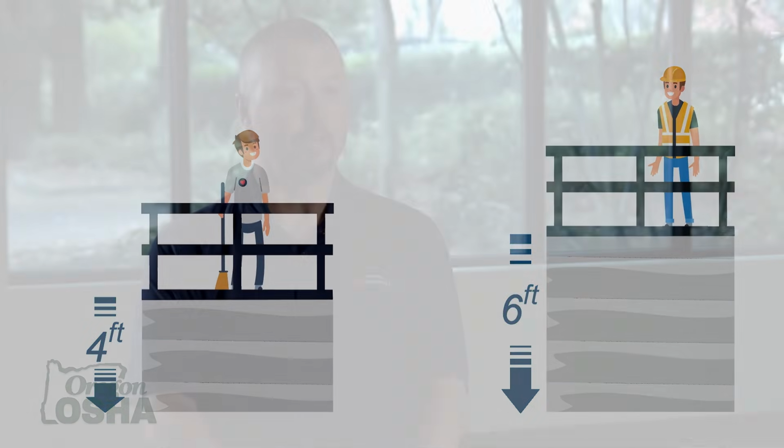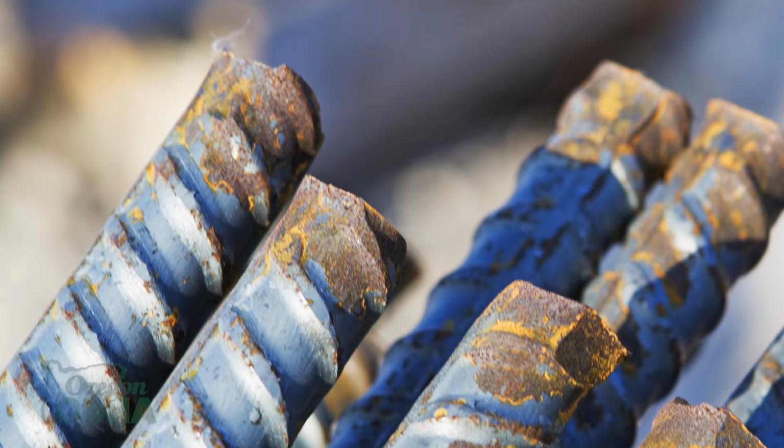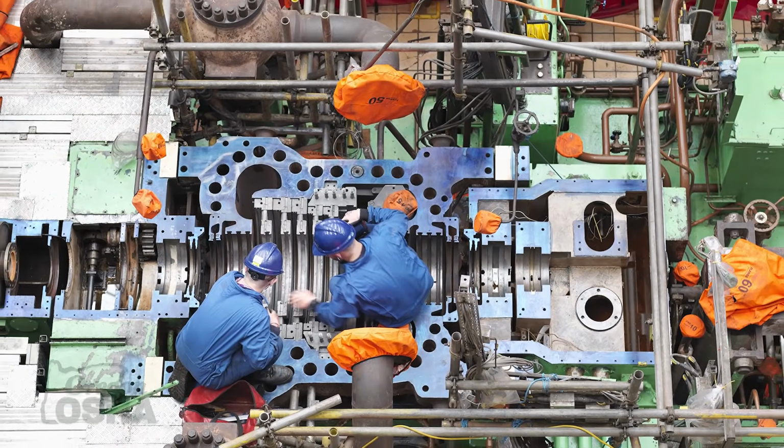But we also have the trigger height of any time there's a hazard below us, whether we're at 4 feet or 6 feet or 3 feet. If there's a hazard below us that we could fall into or fall on, then we need to keep those workers protected. And it's really best for everybody to revert back to whoever the controlling employer is, whoever is setting up that safety program, and see what trigger height is being used for that business, that company, or that activity by that employer.